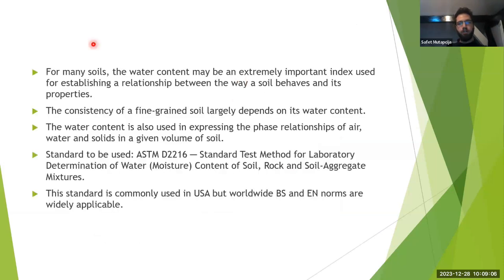For many soils, the water content may be an extremely important index used for establishing the relationship between the way soil behaves and its properties. The consistency of the fine-grained soil largely depends on the water content. The water content is also used in expressing the phase relationship of the air, water, and solids in a given